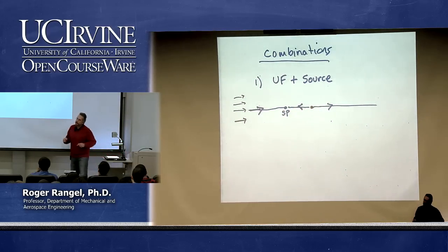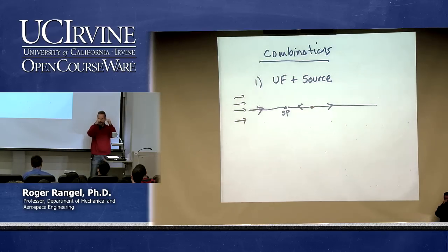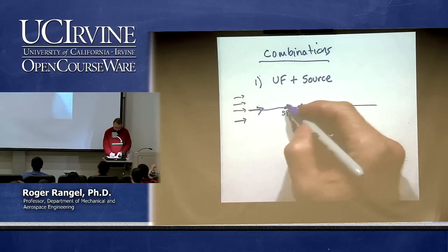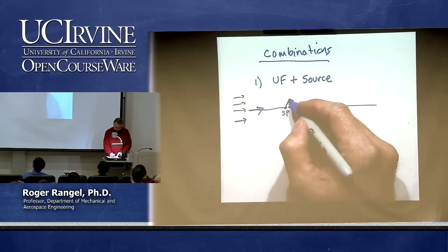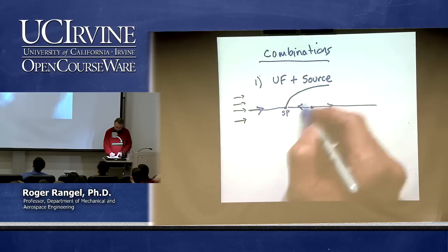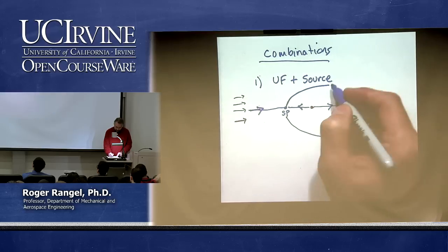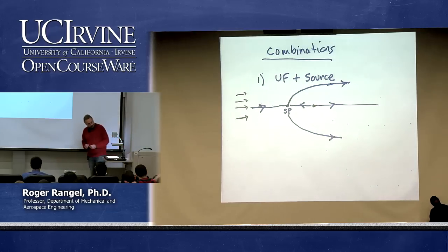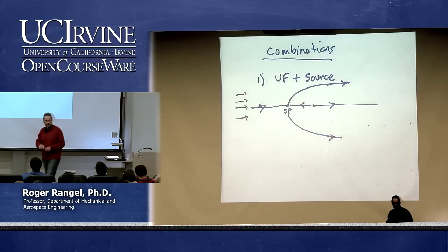And therefore there is a point there where they exactly match each other and cancel out, so you get the stagnation point there. But then we also find that if you follow the streamline that comes out of that stagnation point, it goes like that. Right? And of course I can put more streamlines.